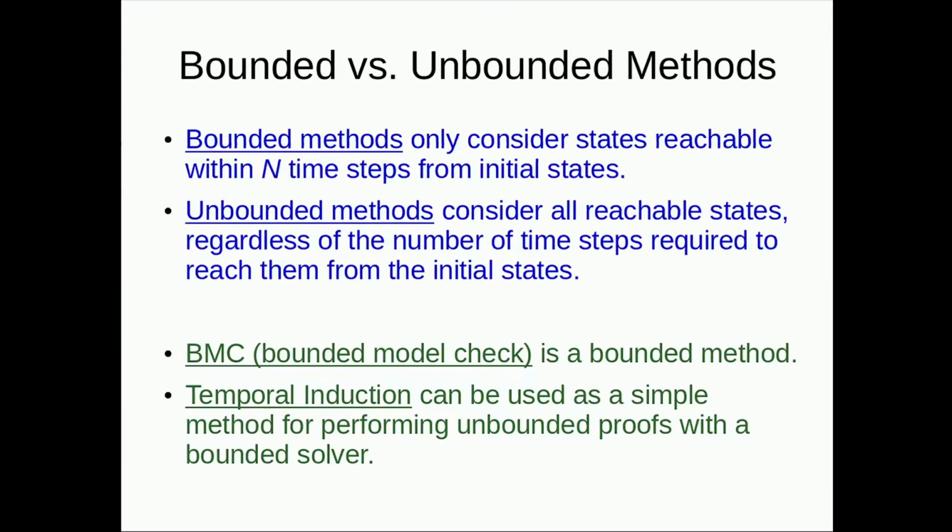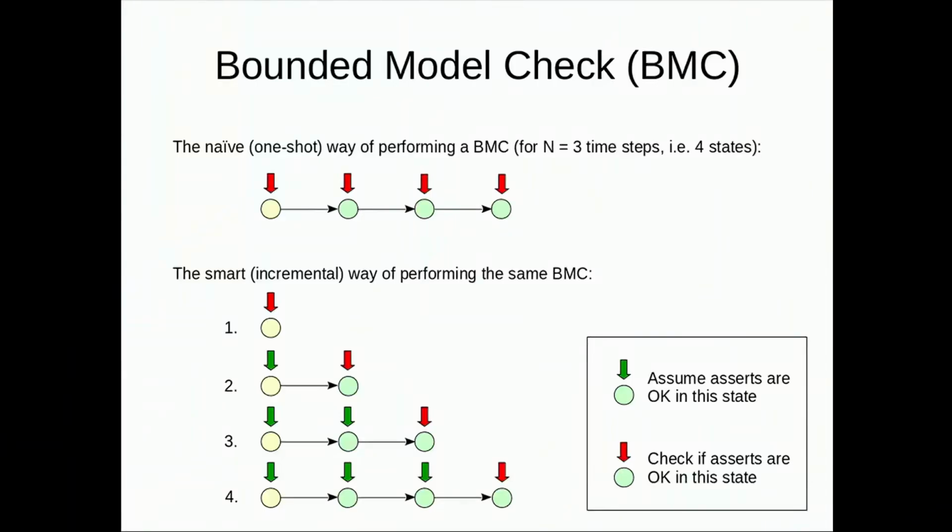So BMC, which is part of the Yosys-SMTBMC name, is a bounded model check. That's a bounded method. And temporal induction is a mechanism that builds in a way on a bounded model check and extends the validity of the check for forever. Let's have a look how we can do that.